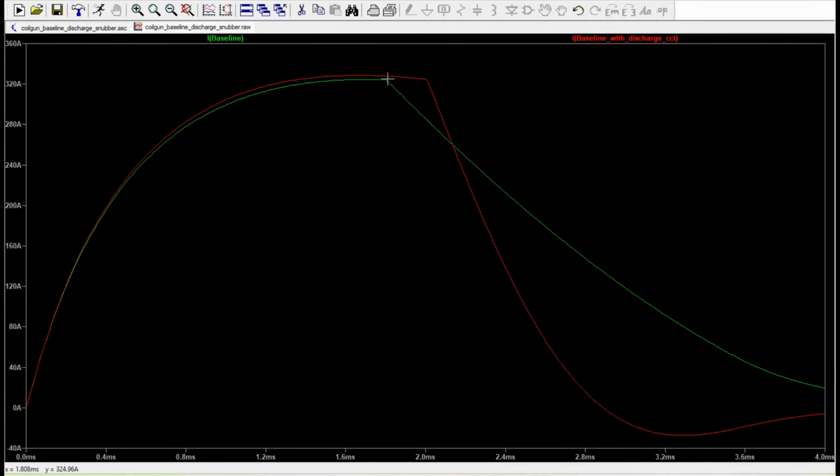In these scenarios, the optimum time to switch the power off was at a point prior to the projectile reaching the center, where some of the recirculating current was contributing to accelerating the projectile, but also allowed time for that current to taper off before it passed the center, minimizing the force decelerating it.